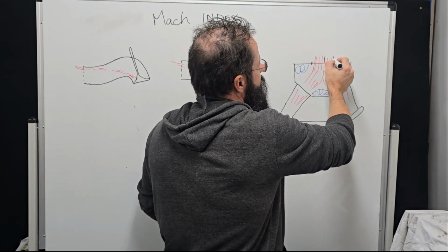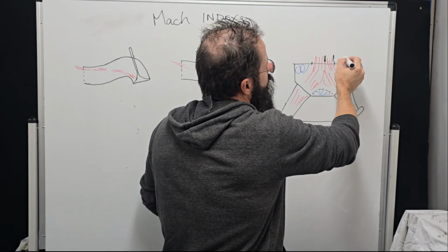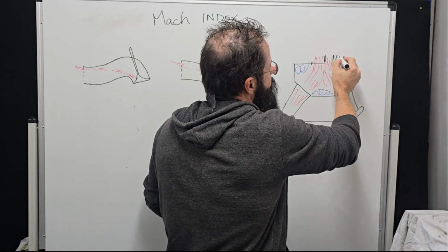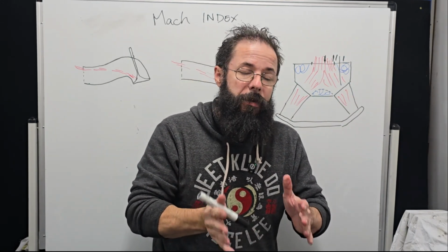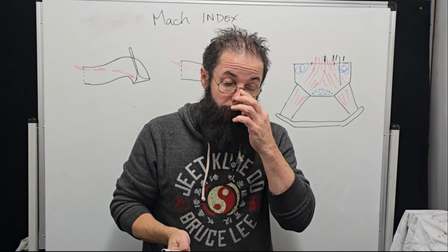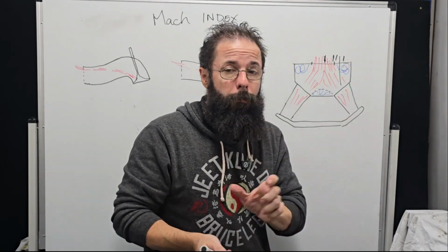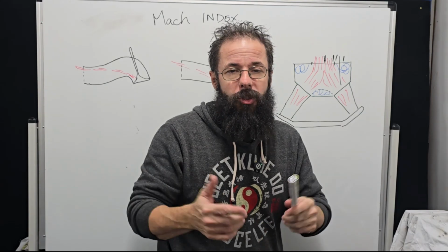So if that's the bore, that bore really should be out here, right? I like 75% of my booster bore to be over the runner, just as a general rule.